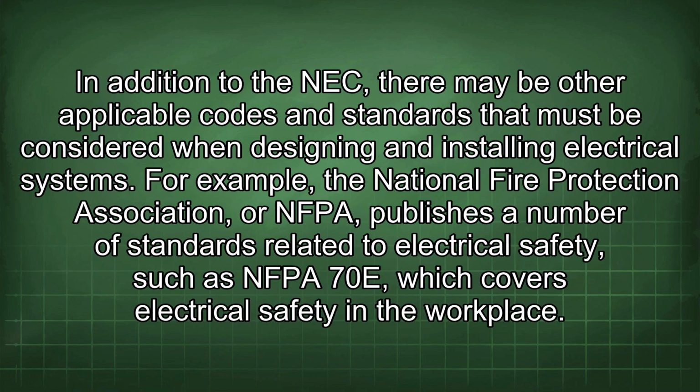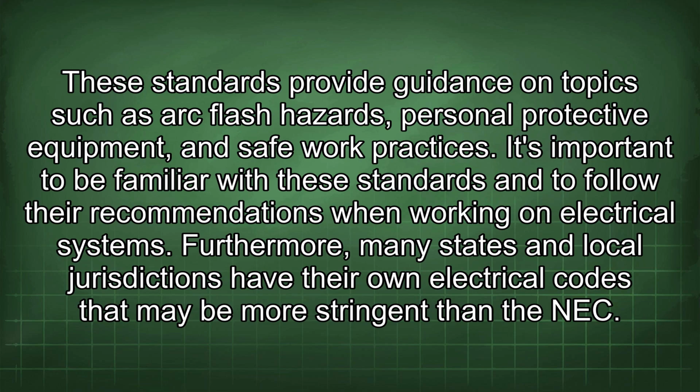In addition to the NEC, there may be other applicable codes and standards that must be considered when designing and installing electrical systems. For example, the National Fire Protection Association, or NFPA, publishes a number of standards related to electrical safety, such as NFPA 70E, which covers electrical safety in the workplace. These standards provide guidance on topics such as arc flash hazards, personal protective equipment, and safe work practices. It's important to be familiar with these standards and to follow their recommendations when working on electrical systems.